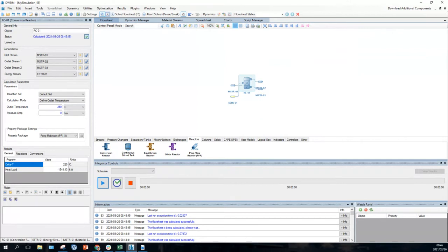Let me go and look at my script notes again, the PDF that I posted this morning. Add a new chemical reaction, that's fine, we got there, we finished with that dialog box. Return to, and we define outlet pressure. And now we can drag and drop, so we're done. Mass flow of methanol should be 2520 kilograms per hour.